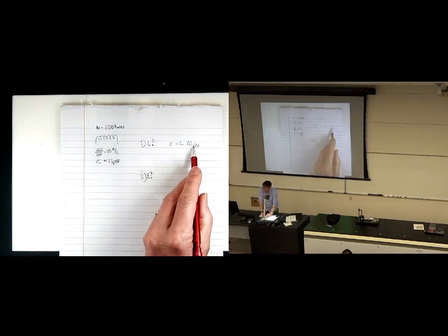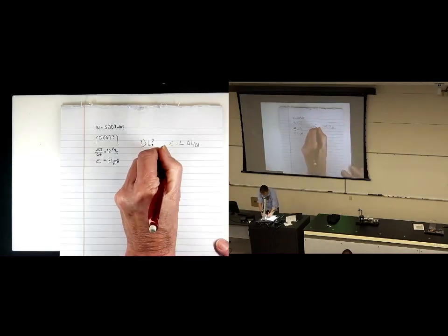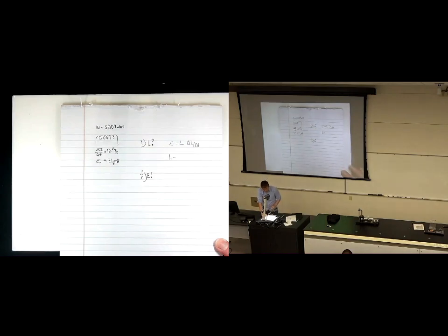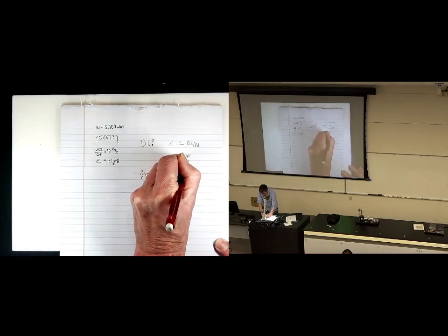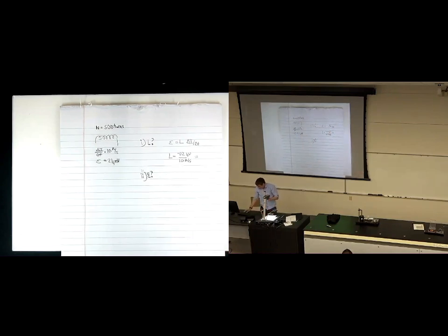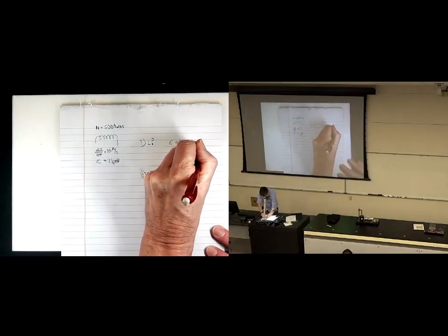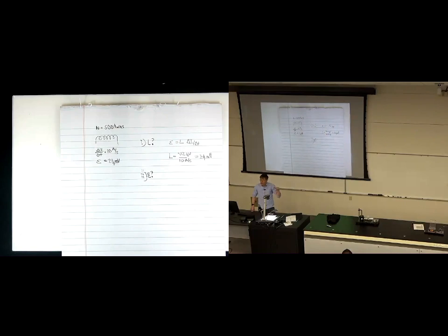Now look, we know the rate of change of current, we know the induced EMF, so we can use this observation, you get 24 millivolts when you change the current by 10 amps a second, to calculate the self-inductance. So it would simply be 24 millivolts, so that's 0.024 volts, divided by 10 amps per second. And if we do that calculation, I got a value that's 2.4 millihenries. So it's 2.4 times 10 to the minus 3 henries.